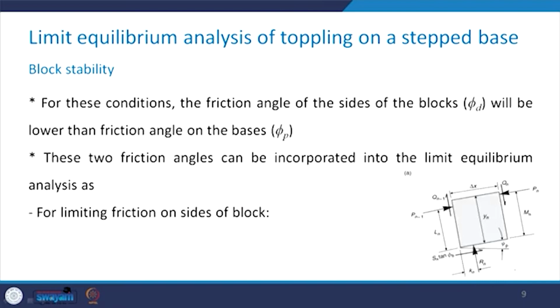So, for such type of conditions, the friction angle of the sides of the blocks is being represented by phi d. This will be lower than the friction angle on the base, which is phi p. Now, these two friction angles can be incorporated into the limit equilibrium analysis as we are going to discuss.